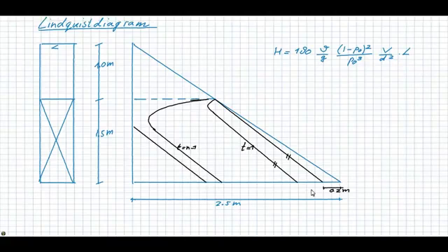This point is critical because below this point, which we call the zone of negative pressures, there is a risk of air coming out of solution, disturbing the filter bed. The total pressure drop can then be around 1 to 1.5 meter. In practice, however, we keep the maximum allowable pressure drop equal to the maximum supernatant water level to avoid these negative pressures and also to avoid the water level from dropping below the filter bed.